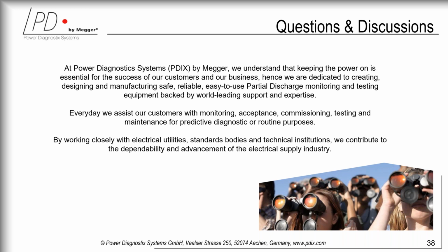I know we did find failures in composite bushings in the past, some of them during factory acceptance tests, some of them at site. The signal received from the bushing is similar to the signal that we see from a calibrator signal. So we can see from the spectra and from the pulse shape analysis of the PD signal where it comes from approximately.